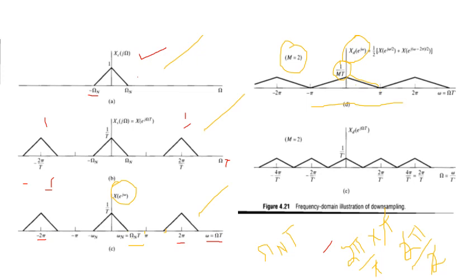Obviously, when we do that, these 2 points will join up, because if our sampling frequency is 2 times the maximum frequency, we will have that much gap; otherwise these 2 points will join. So as I've told you, this is π and this is also joined, so our spectrum is stretched up, as you can see here.